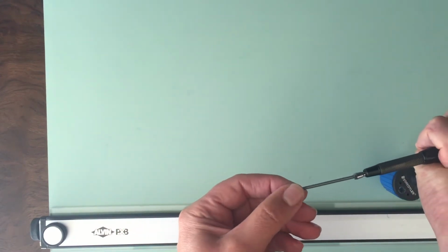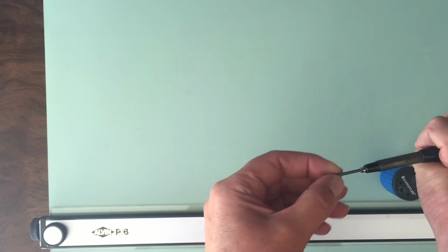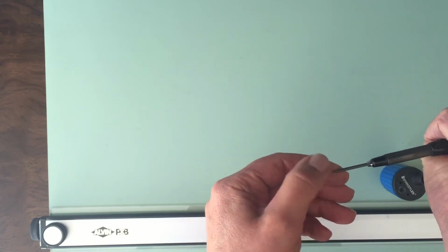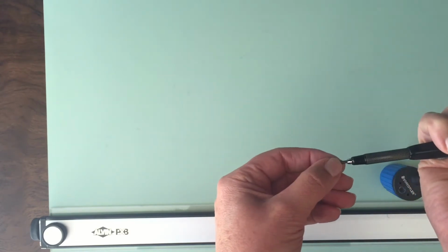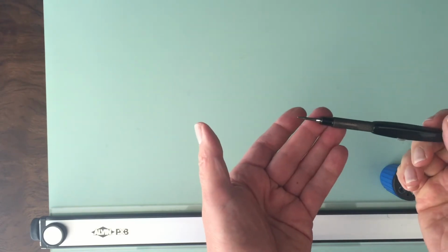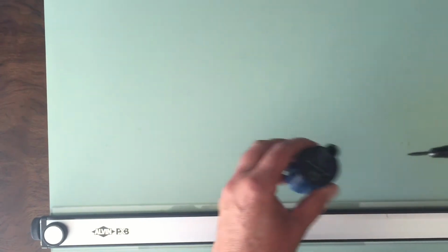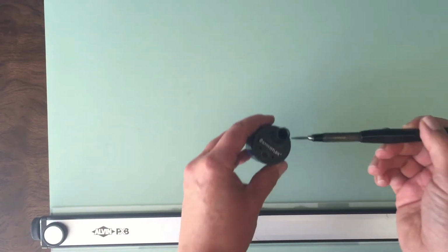And this comes in very many different hardnesses and softnesses, these leads here. I prefer to draft with an H lead because it allows me to have nice light lines, and I can also use very dark lines, which I'll demonstrate in a bit. So to sharpen these pencils, and it's really important to keep our pencils sharp,